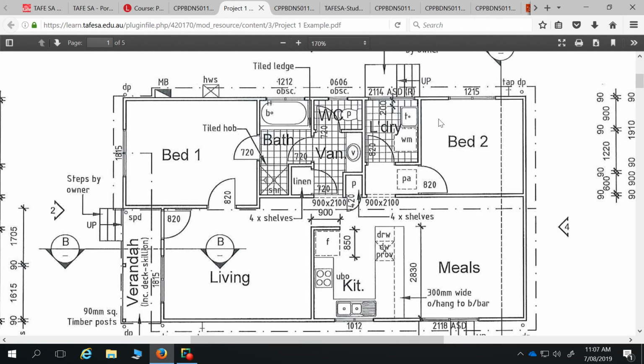And I'll show you in Revit how we can actually get this to populate for a window automatically. We can use what's called, it's a tag, but it's called a multi-category tag. And when you use a multi-category tag, you assign a number to that window so that it'll come up next to the window automatically. And if we use that window again and just go multi-category tag, it will come up automatically the number that is associated with that family. So I tend to use multi-category tags in planning drawings all the time and do them a bit like this because that's all the info they need.